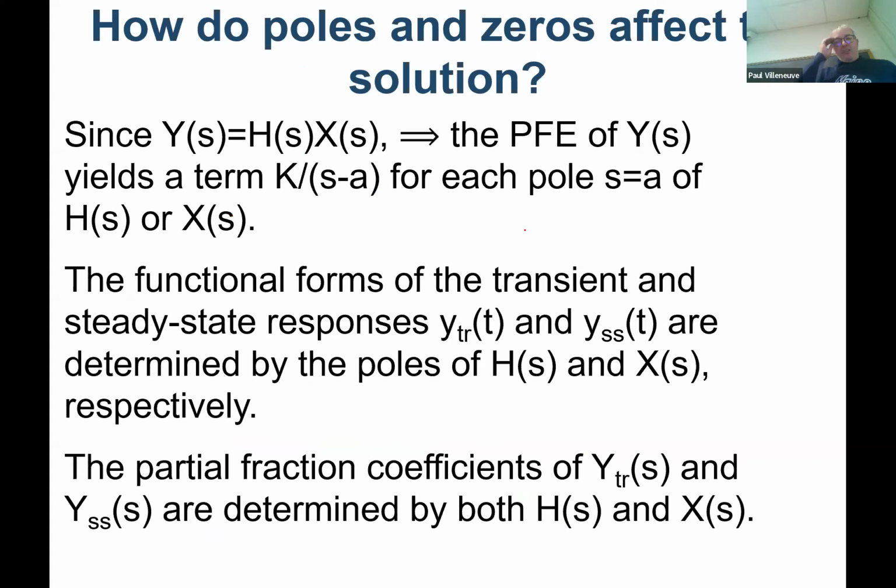So the poles and zeros, like we said, we talked about having a transfer function that has an actual system response. That's denoted as the transient response. That's how the system dies or does whatever it's supposed to do, or increases exponentially. My steady state term is based on what the input is. Okay, and knowing the poles, you can see the poles of H. That's going to give me my transient response. The input, which we'll call X, that's going to be the steady state response. That's what's forcing it, because we have to continue to supply energy.